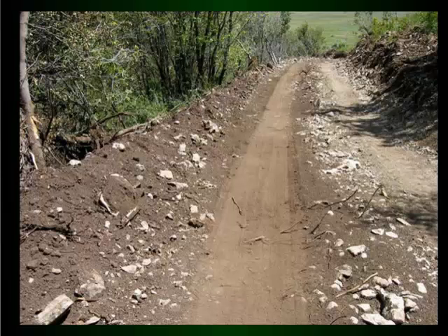This is one of Darren's slides. I think this is the project where the guy designed the road from the cat, saw where he wanted to go and just got on it. You see a lot of this berm action, and this is on a brand new road, so obviously that berm's probably going to be there to stay. And it gets a little bit muddy, and so they make a pass with the blade, and they make another pass with the blade, and the berm gets higher, and the berm gets higher. And pretty quick, the road's the lowest thing around, and so it becomes a stream bed.